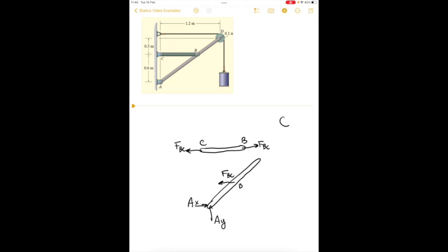So I'll draw pulley D first. There's the tension in the cable, which is equal on both sides. And there's the connection at pin D. If I draw it this way, then I draw the opposite here. This is the reaction back from the pin D on the pulley. And finally we can draw the cylinder, which has a weight and the tension.